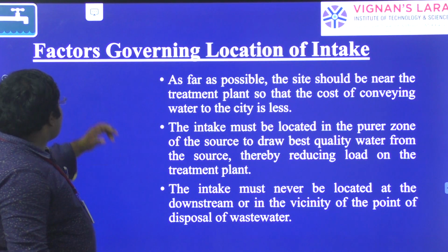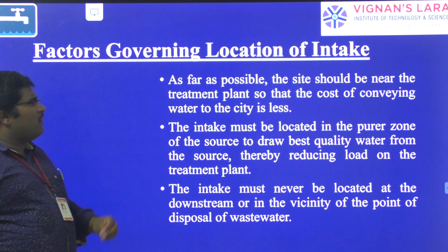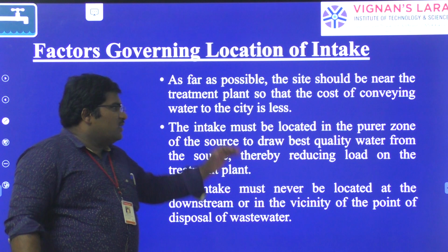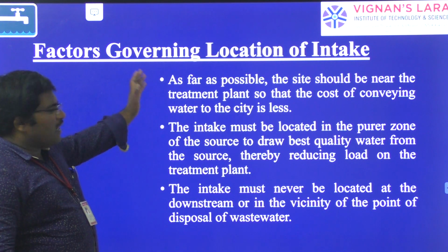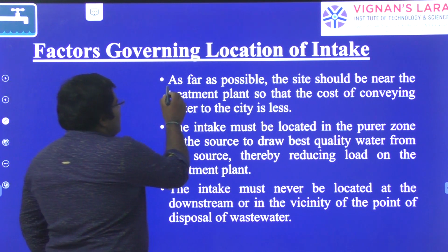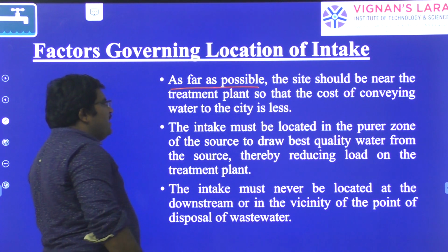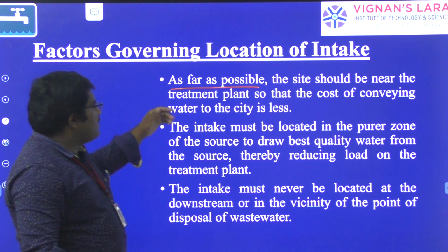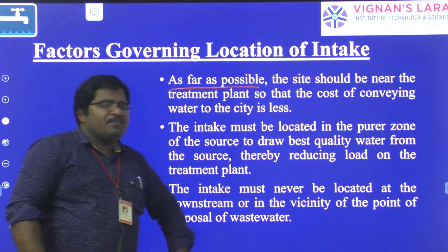Next point. What are the factors governing the location of the intake? From the exam point of view, this is very important. The first thing is, as far as possible, the site should be near the treatment plant so that the cost of conveying water to the city is less.